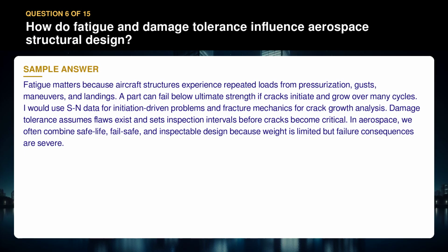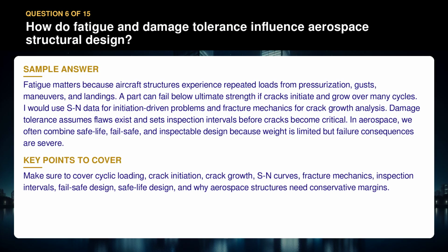I would use SN data for initiation-driven problems and fracture mechanics for crack growth analysis. Damage tolerance assumes flaws exist and sets inspection intervals before cracks become critical. In aerospace, we often combine safe life, fail-safe, and inspectable design because weight is limited, but failure consequences are severe. Make sure to cover cyclic loading, crack initiation, crack growth, SN curves, fracture mechanics, inspection intervals, fail-safe design, safe life design, and why aerospace structures need conservative margins.